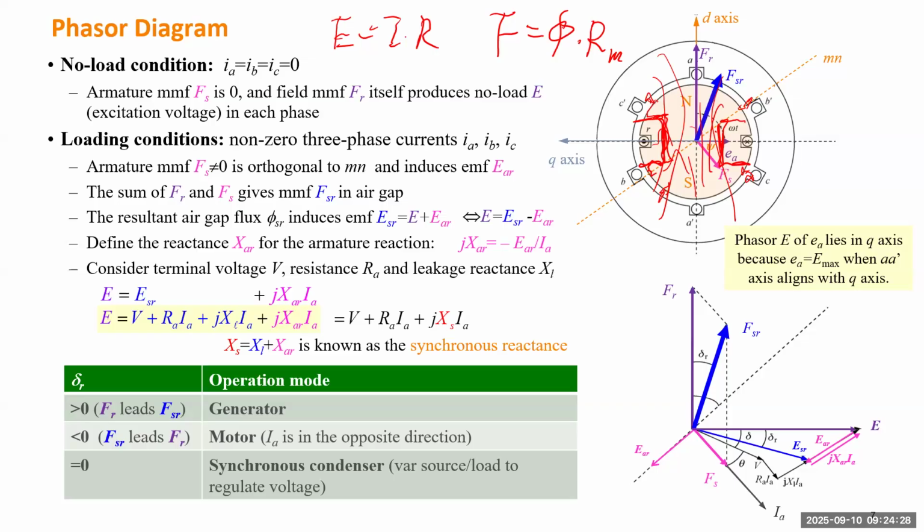So which means for a salient pole rotor generator, when it revolves, winding A will sometimes face the poles, either N or S, so the air gap will be smallest. But for the quadrature direction, it will have the largest air gap. So Rm here is also periodically changing relative to the position of the rotor. So we have to discuss that for the salient pole rotor generator.